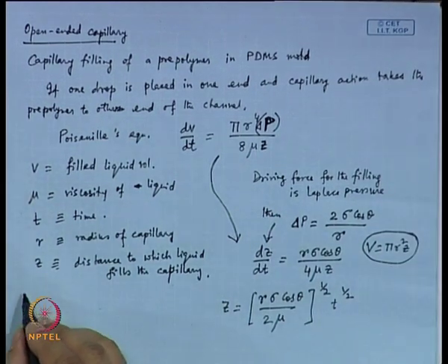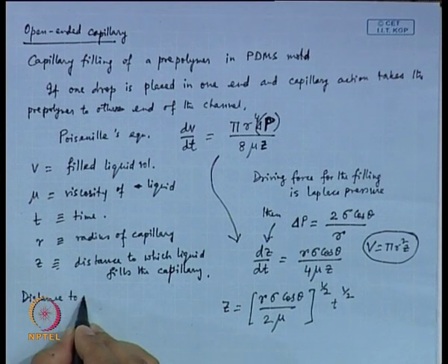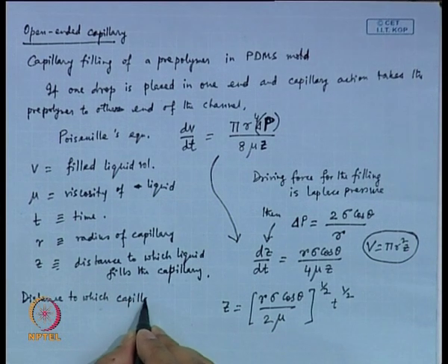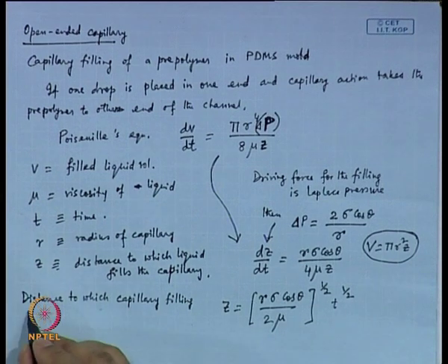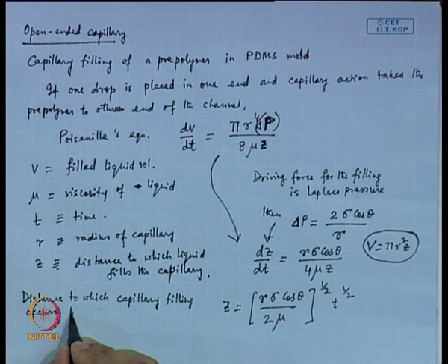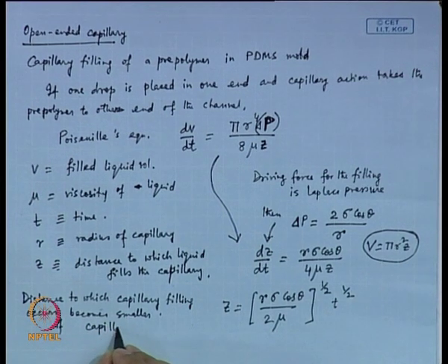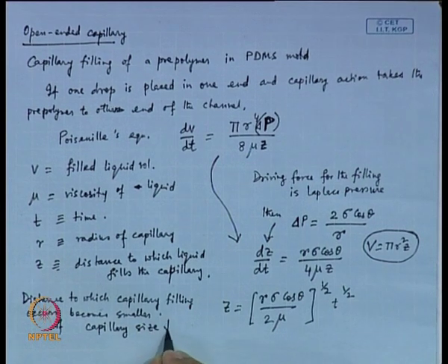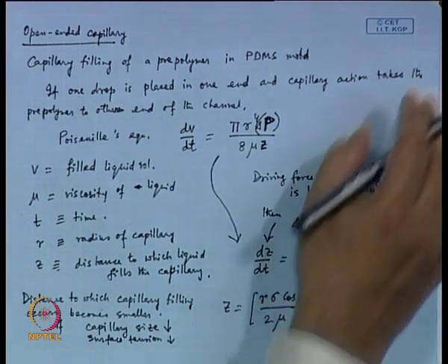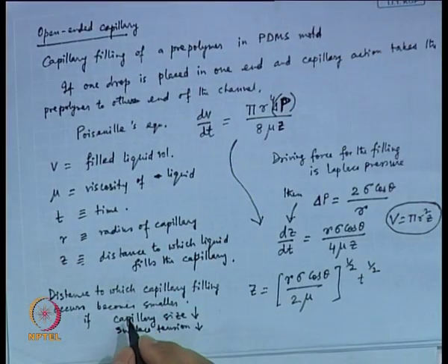One thing I would like you to appreciate here is that the distance to which capillary filling occurs becomes smaller if capillary size goes down, if surface tension goes down, if contact angle goes down.